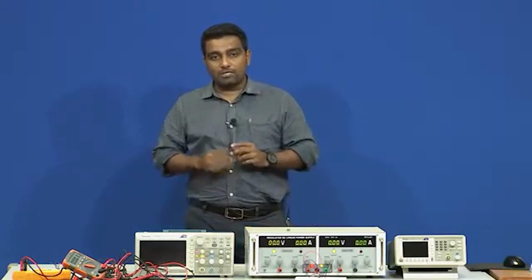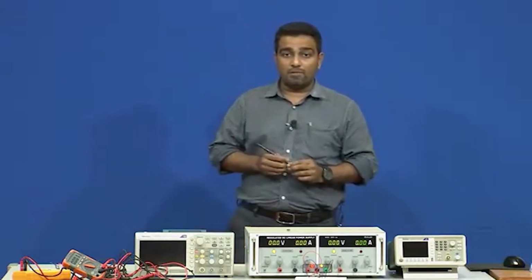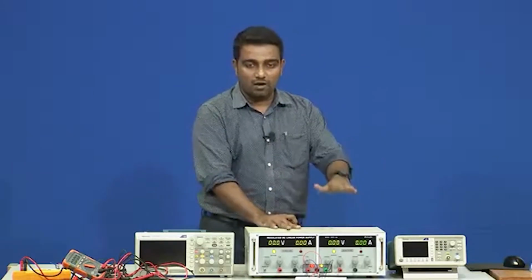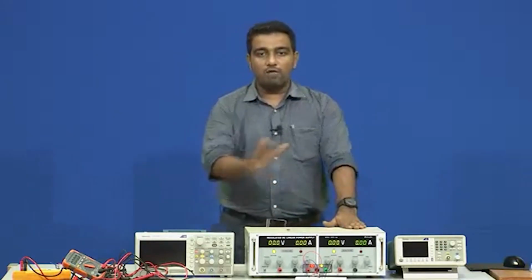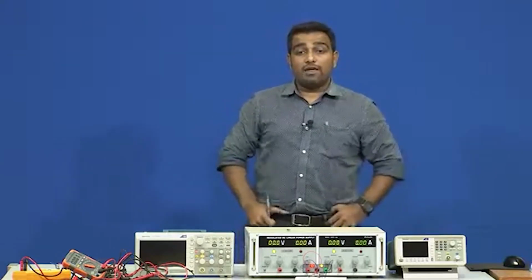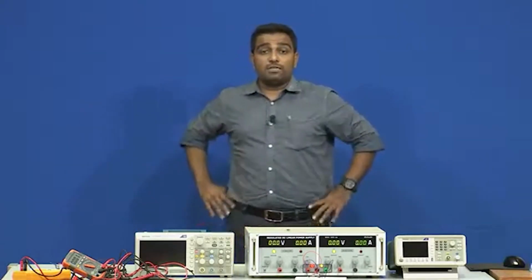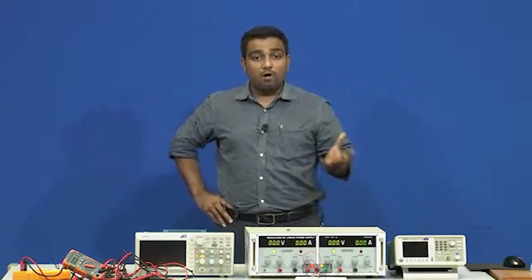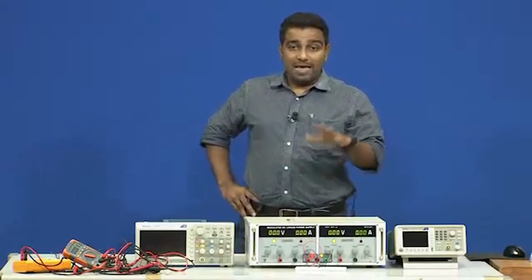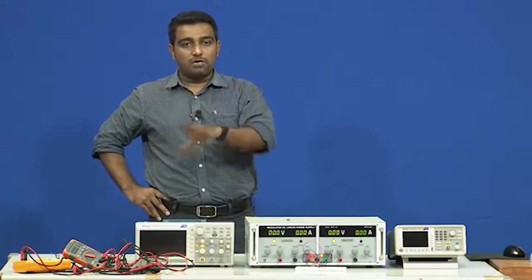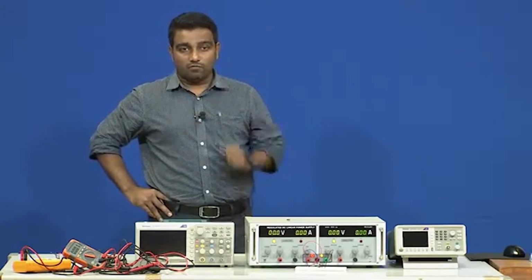But when you actually measure the operational amplifier by testing this particular experiment, that is, you give inverting terminal ground, non-inverting terminal ground, and you measure the output voltage, what you will find is that the output voltage is not 0. So, if the output voltage is not 0, how can we make it 0? The voltage required at the input to make output voltage 0 is your offset voltage. This is what offset voltage means.